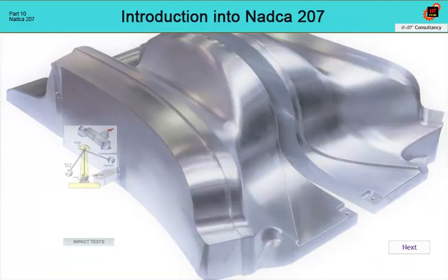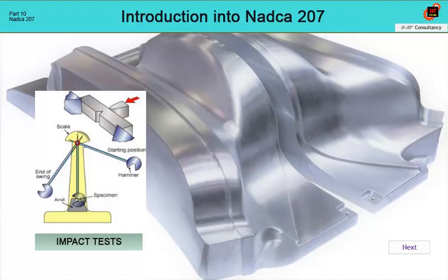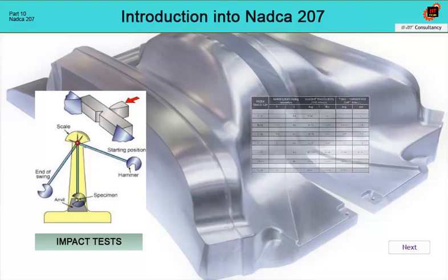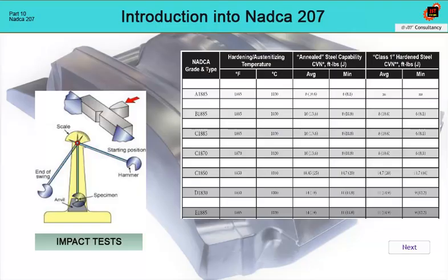A condition for solving tool life is strict testing of the input material and verification of the material after heat treatment. Testing is usually carried out through impact tests, and it is precisely specified what values the selected material should achieve before entering production, and what values should be achieved after heat treatment. If the test results are within the recommended range, then the life of the mold should correspond to this.